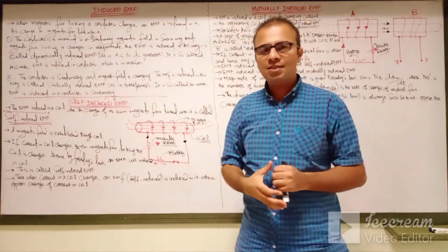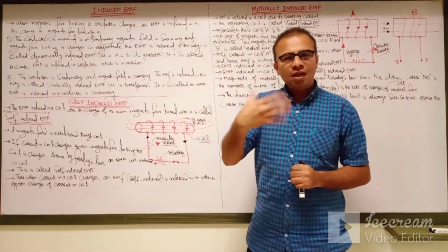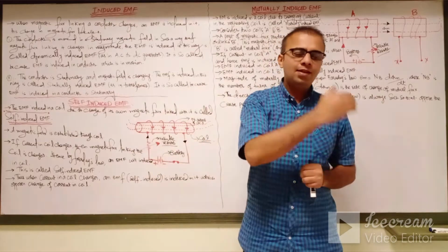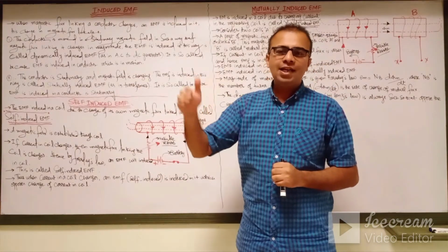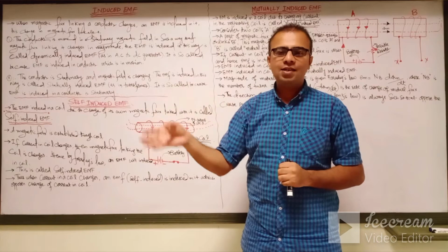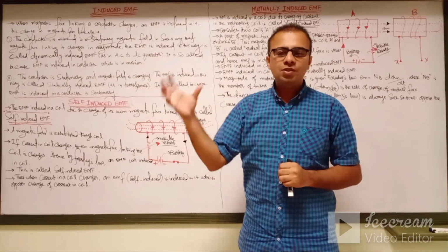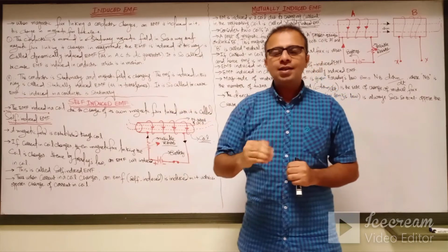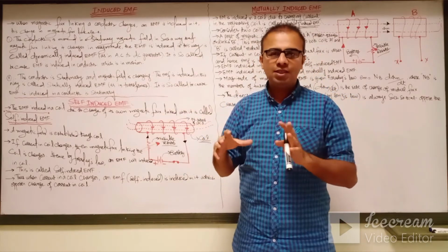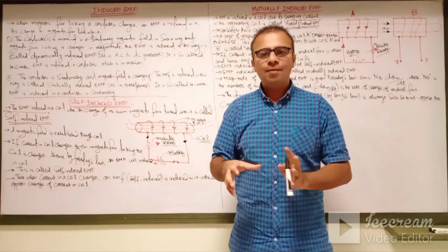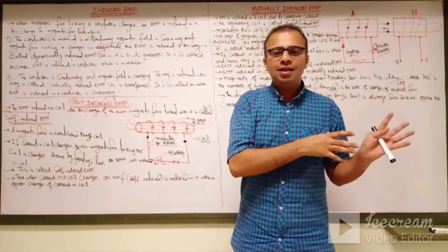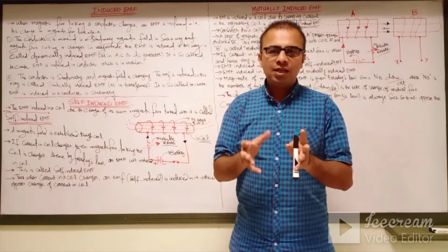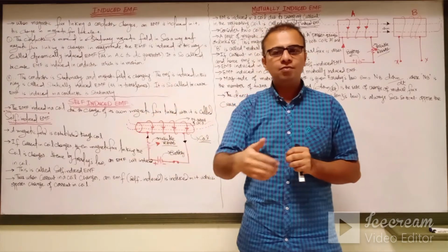If we take the DC generator, then a DC generator comprises two windings, the field winding and the armature winding. The field winding is a stationary winding which is excited from the DC supply to produce magnetism. And the armature winding is the rotating winding, because in generator action we need the prime mover to convert the mechanical energy into electrical energy. This is the property of any generator, either DC or AC.